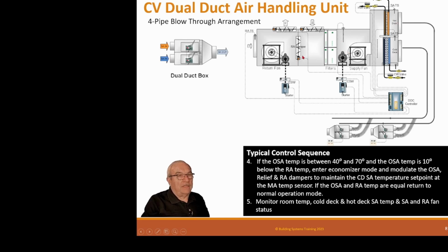So this is exactly like the last unit, where these units modulate together to maintain a room temperature and try to maintain the supply volume the same. So this damper modulates with this one, so that if this is open 50%, this will be open 50% to allow this fan to go out this way. Remember, this is a constant volume fan, so it doesn't change speed. So you have to set these up so that when this outside air is coming in, you have an equal amount of relief going out, so we don't change the temperature here. And this has to be balanced that way. And this is really a tricky balance condition. And this really proves if your balance guy's really good or not, if you can set that up correctly.